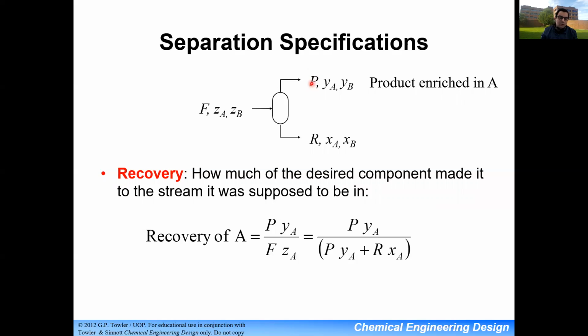And again, here I'm using P, which most of the time is pressure, but this is actually the molar flow rate. So this is your molar flow rate, and this is your molar flow rate. Here P refers to product, sorry. So it's basically the molar flow rate from the top stream multiplied by the fraction, divided by the flow rate of the bottom stream multiplied by the fraction. Again, just be careful that if your feed is a liquid and your top is a gas, you can use the pressure and the vapor pressure idea as well. Just make sure your units match, okay?